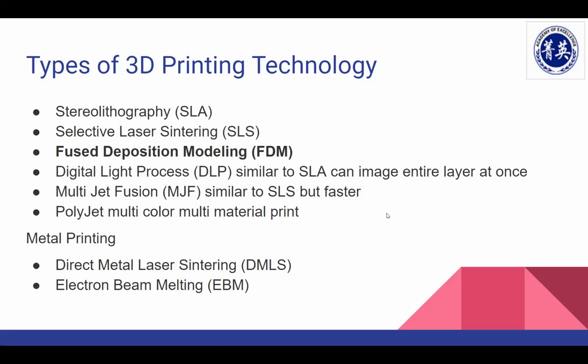Now we mentioned industrial. Well, to understand 3D printing, there are a few different types. SLA, which is what the terms are standing for right there, is basically resin-based 3D printing. So you have a laser that runs on a pool of resin that sits on a building bed. Each layer, the laser will harden the resin layer by layer and move down, right? So it's very similar to the filament printer we just saw in the video a minute ago.